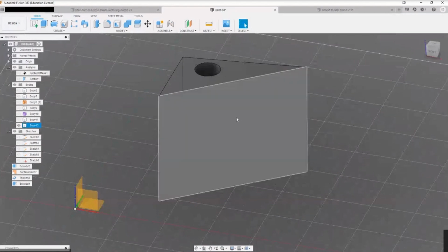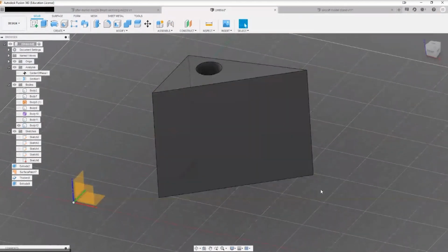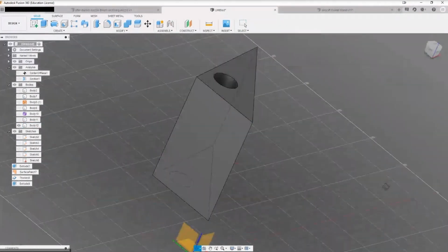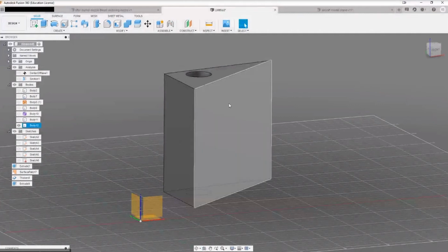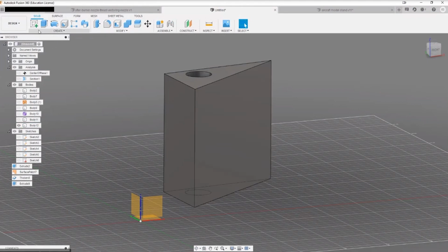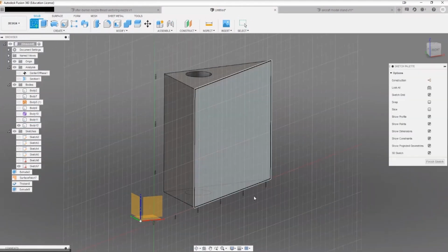Okay, for example, if you wanted to create another sketch that's off this face, okay, and this is where I get into the part of managing your sketches. If you've got multiple sketches looking in this direction where you need to do something, there's 2 ways you could do it. The messy way would be you would create a sketch on this plane.